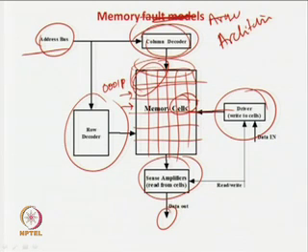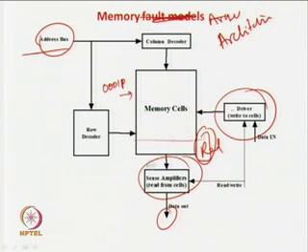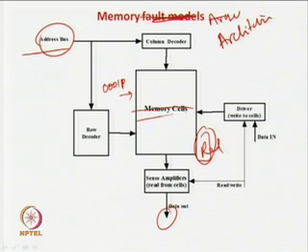The components are the memory cells, which are the stacked part, quite different from our normal sequential and combinational circuits. And as I already told you, there is some redundancy here. If some part of the cells gets damaged, it will reorient the connection by blowing fuses, as we discussed, so that there is a bypass. Say this part of the memory cell has gone bad.